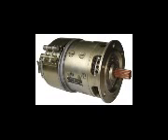The speed of an aircraft engine varies from idle RPM to takeoff RPM. However, during the major portion of a flight, it is a constant cruising speed. The generator drive is usually geared to revolve the generator between 1 and 1½ times the engine crankshaft speed. Most aircraft generators have a speed at which they begin to produce their normal voltage. Termed the coming-in speed, it is usually about 1,500 rpm.